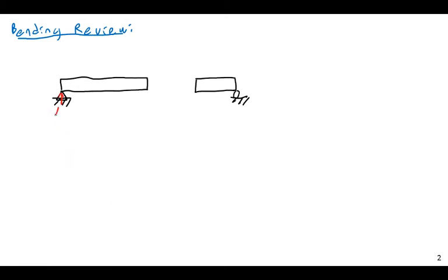Okay, then we have, say, an Ay here, maybe a By, and we have a constant line load across the top of this. Or it could actually be just any kind of distributed load here. So I drew this as a constant function, but let's just say this could be any arbitrary w of x. And then inside the beam, we will assume when we initially draw this positive shear and moment according to the sign convention that we have discussed previously.